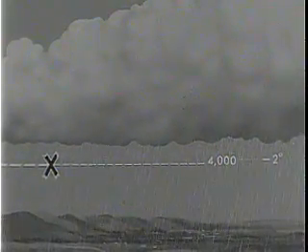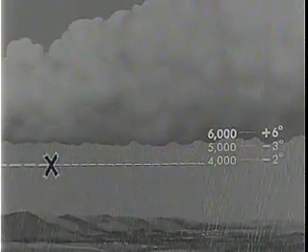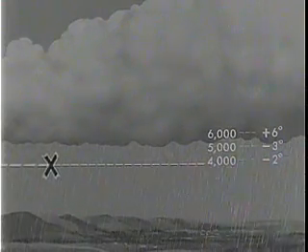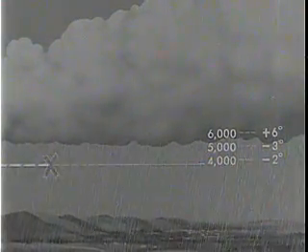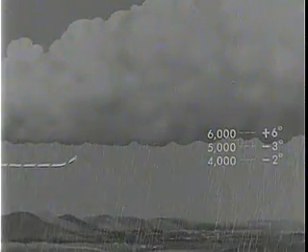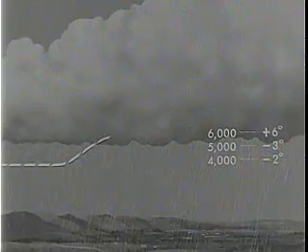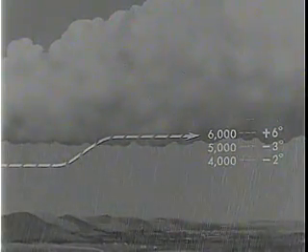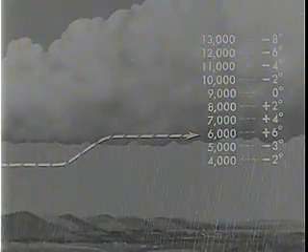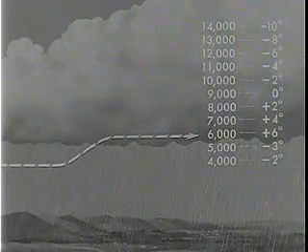In this case, if from your pre-flight briefing you know the location of the warmer air from which the rain is falling and can reach it quickly, you may climb out of the freezing rain. As soon as you reach above freezing temperatures, you should level off and proceed at this altitude, because applying the temperature lapse rate rule, you know that higher in the cloud, icing conditions will again be encountered.